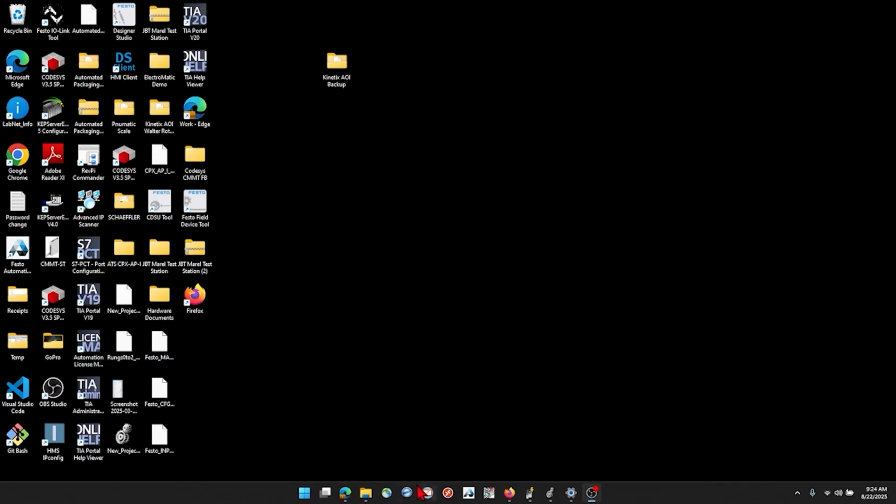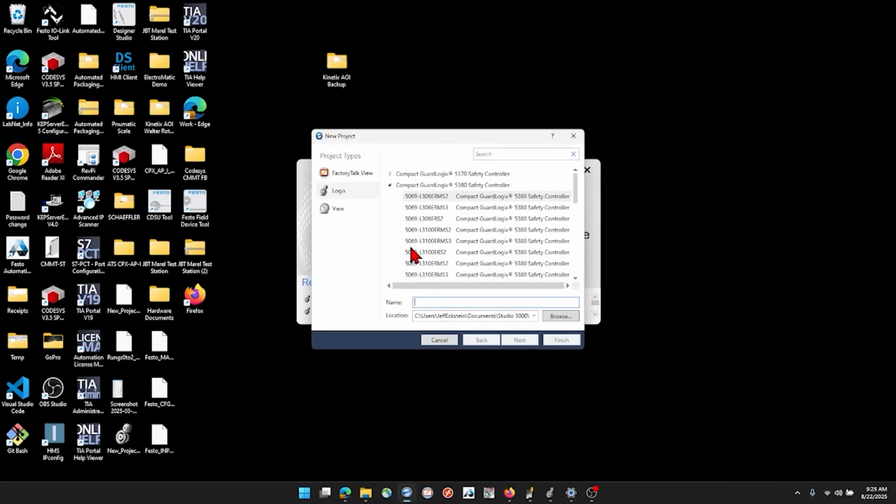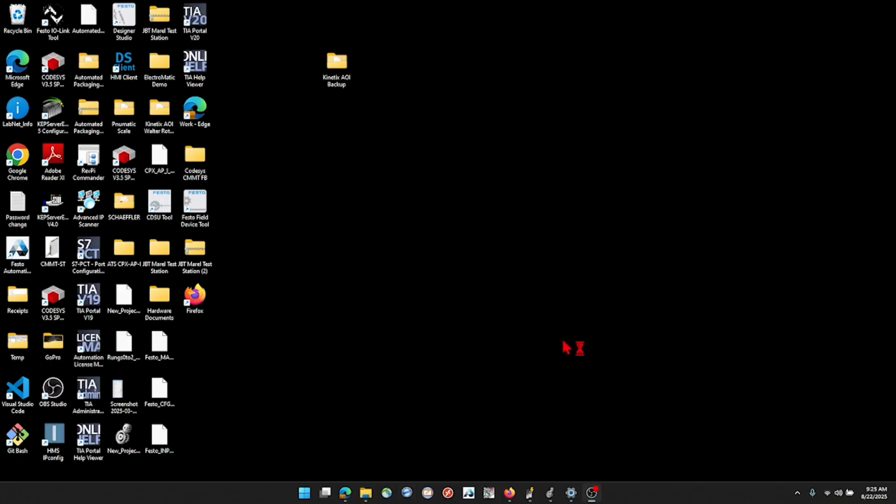And then we'll go ahead and open up a brand new project in Studio 5000. So pick the appropriate PLC and then give it a name. We'll just call this SMS Demo. And then again, I'm working in version 35, so we'll set the appropriate revision, and then go ahead and create this project.